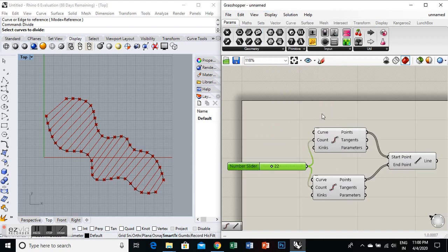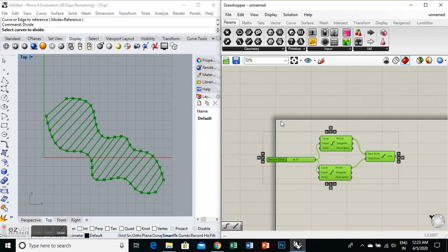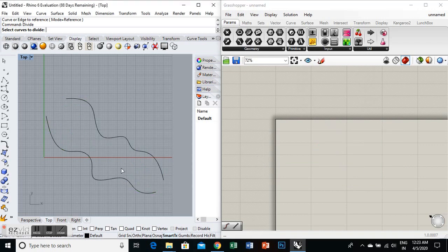You can draw the input parameters and output parameters. You can simply recognize them. So now what we'll do is clear the canvas of Grasshopper, and we'll see how we can refine something. We have made two curves, so we'll make another curve in the middle of these two curves using the curve command. So we'll type curve and we'll draw a curve between these two curves.